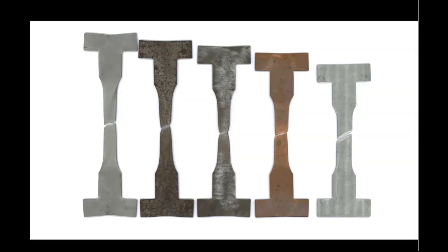So engineering stress is force divided onto the original cross-sectional area, right? And when we think about engineering values, they're, for lack of a better word, flat earth values, all right? So we only consider unchanged cross-sectional area of the sample. So we apply the load, but we assume that the cross-sectional area remains constant.